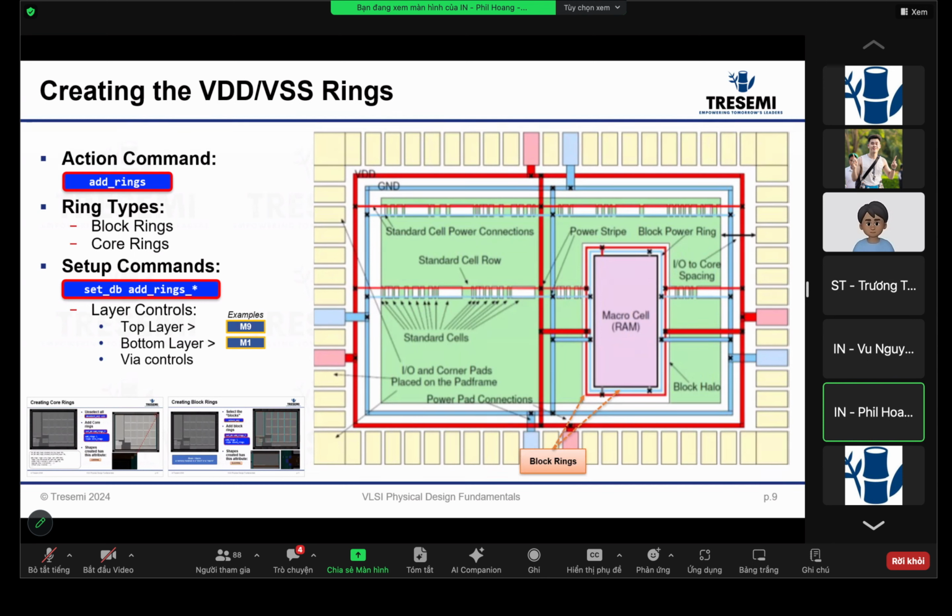Okay, in which case is the VDD of the IO pad lower than the core VDD? Good question. Typically it's higher, because internally you have low voltages, since you want to be as low power as possible, but sometimes you need more VDD to meet the speed.